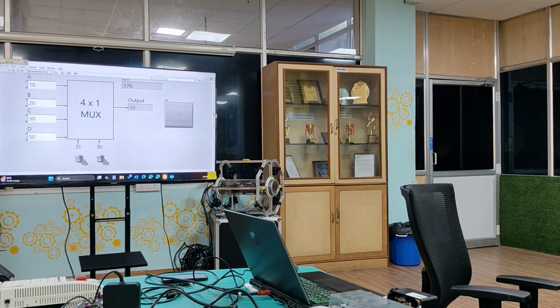This is Tick Count. You right click on an empty space, Timing. Take the first row, third column. Already you have the Wait function. I'm sorry, it has one input, right? Connect the one input to 200.